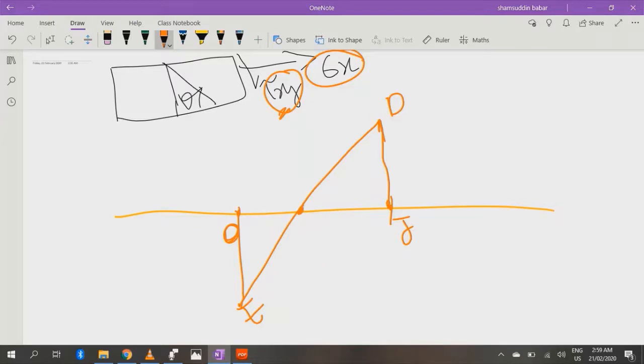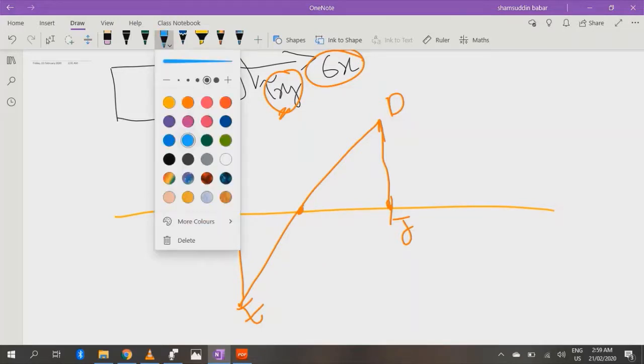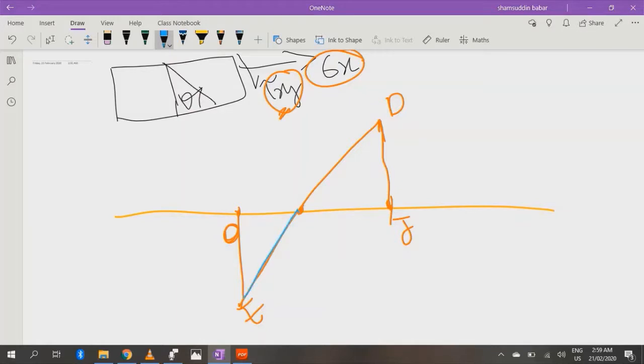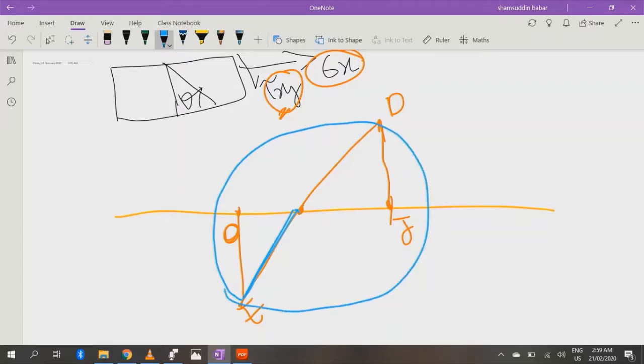For example, now draw a Mohr circle. The radius will be equal to OE. Now draw this Mohr circle. After you have drawn the Mohr circle, from this line in clockwise direction at a 2 theta angle, make a line and name it as point P. This one becomes point P. Drop a perpendicular, perpendicular to this.